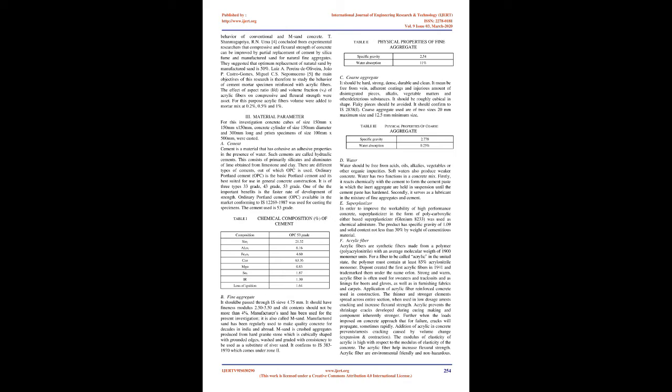Luis A. Pereira de Oliveira, João P. Castro Gomes, and Miguel C.S. Nepomuceno [5]: The main objective of this research is to study the behavior of cement mortar specimens reinforced with acrylic fibers. The effect of aspect ratio, L/D, and volume fraction, VF, of acrylic fibers on compressive and flexural strength were assessed. For this purpose, acrylic fiber volumes were added to the mortar mix at 0.2%, 0.5%, and 1%.